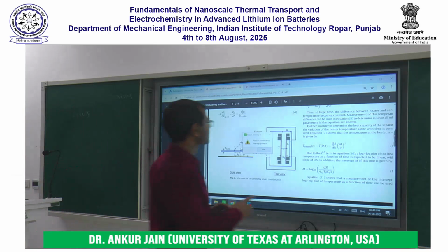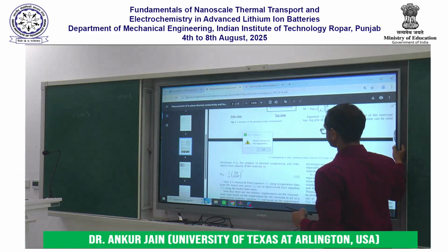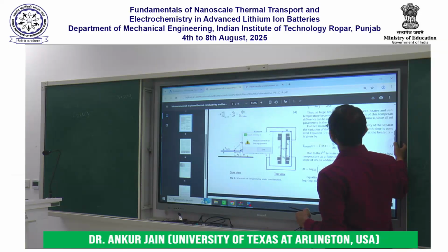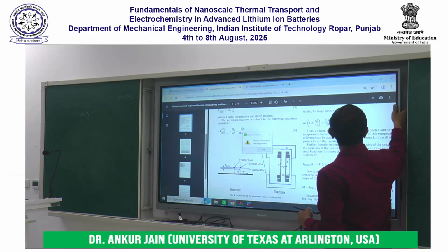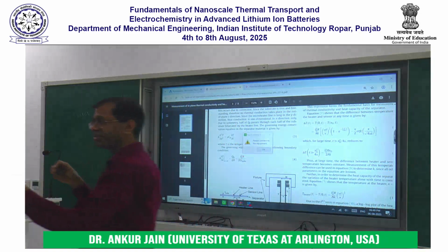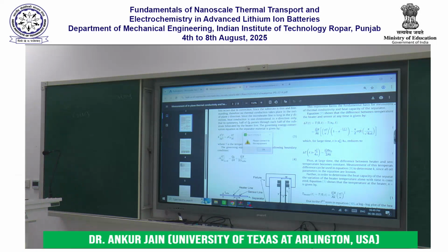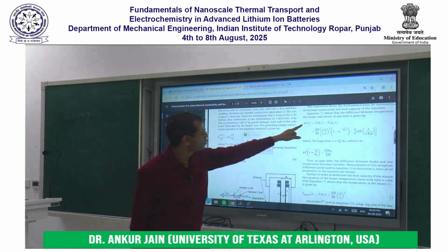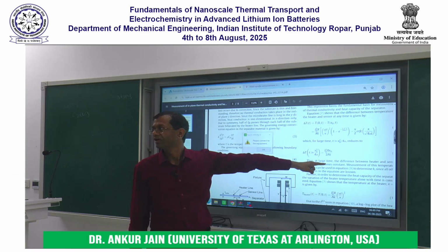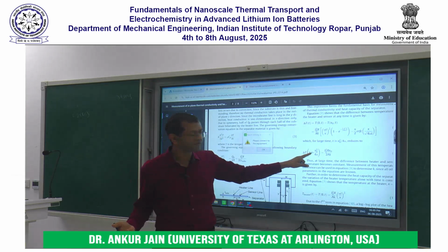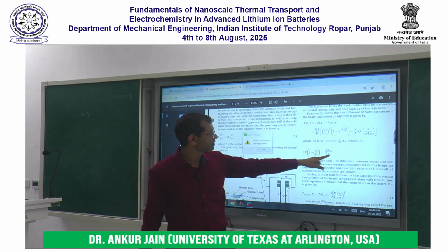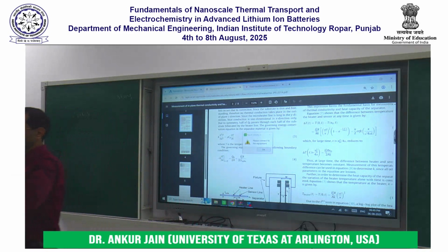Moreover, we also predicted that the temperature difference between the two, the heater line and the sensor line, at large times should become constant, and the steady state temperature difference between the two lines, we showed, has information about the thermal conductivity of the material.